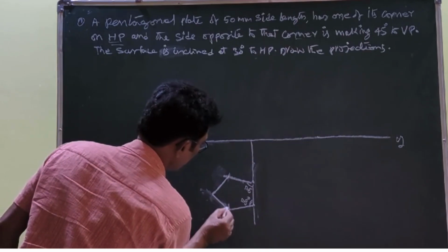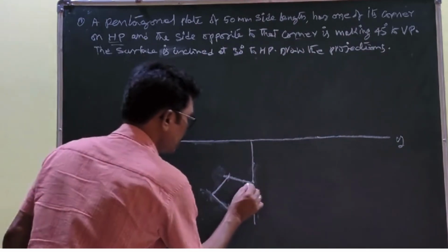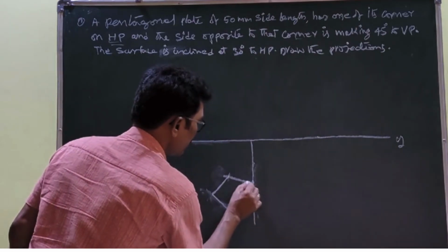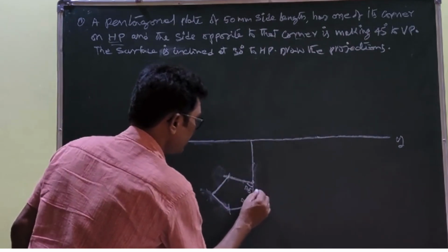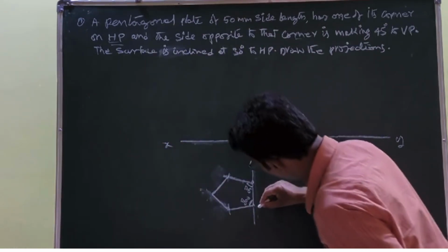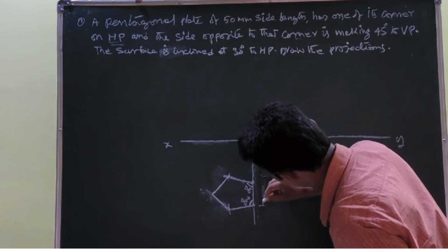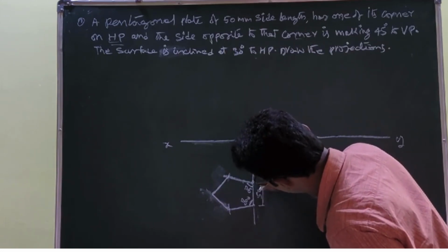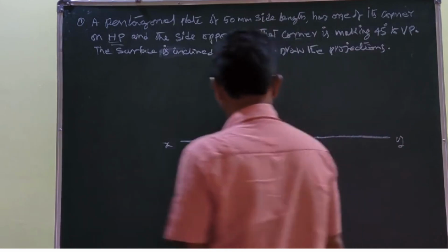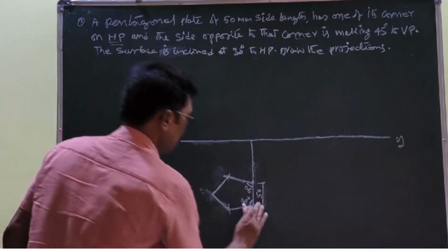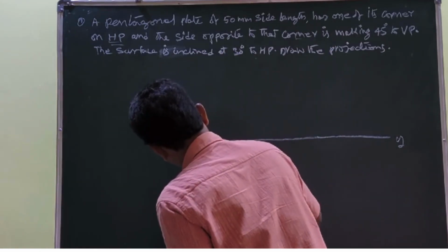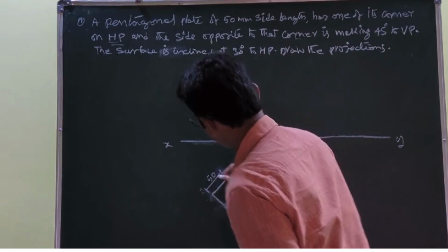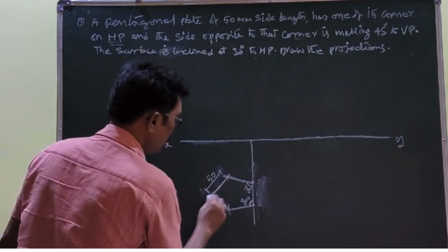Okay, this is okay. Draw the pentagon like this. This is the 108 degrees, then through this you draw a line, this side of the pentagon equal to 50. Or otherwise you can represent it here, this is the 50. Okay, now you construct a pentagon.